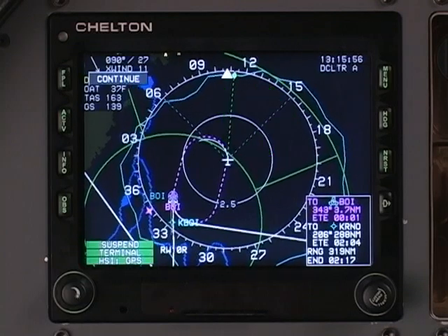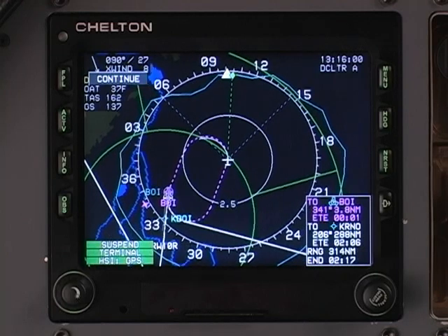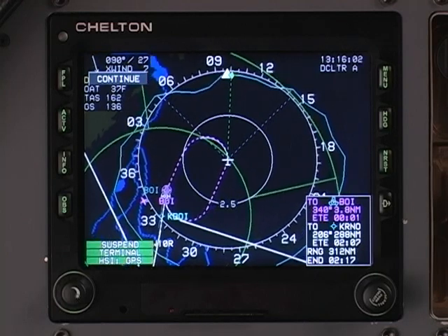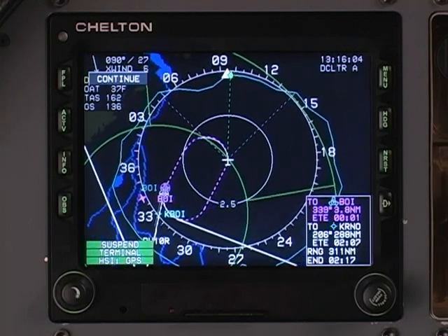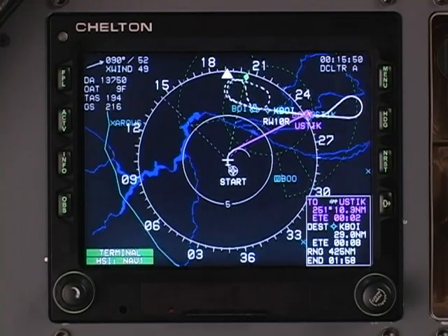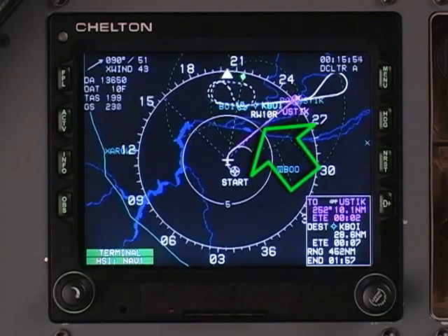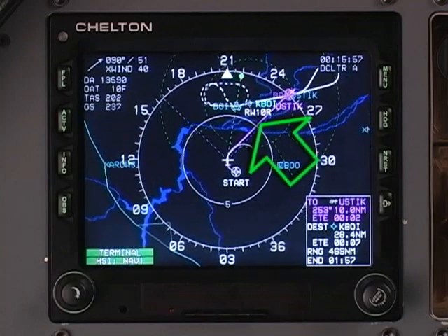Soon you will be able to do it using the Skyway alone. Likewise, use the projected path when intercepting the Skyway at a steep angle until you can do it with the Skyway alone. If you ever lose track of the Skyway, refer to the magenta line on the moving map and keep in mind that the boxes may be above or below you based on your target altitude.